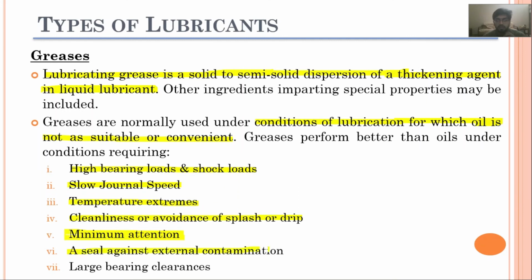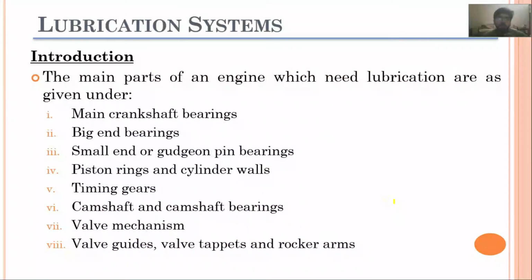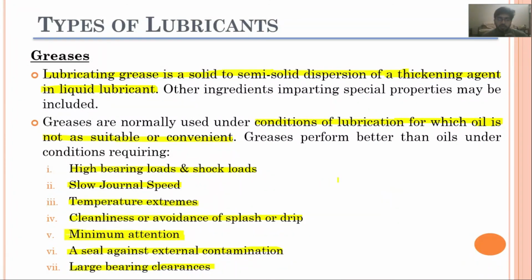They can seal against external contamination. They are also used where we have large bearing clearances. In larger bearings we do not use a lubrication oil, we prefer to use greases. So that was all regarding the types of the lubricants.